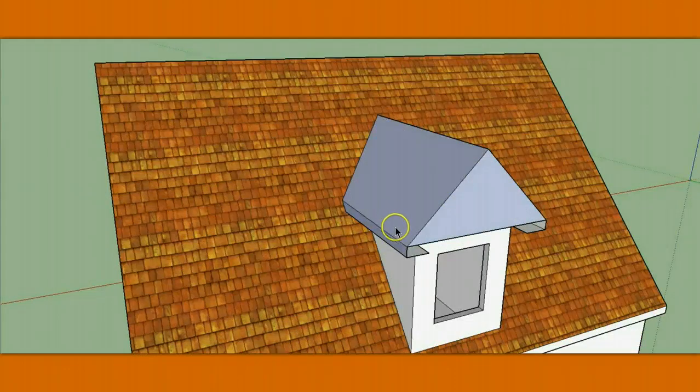Okay, good. Now, obviously, this is your metal roof. Here, this is all half-inch CDX plywood. There's flashing. We have flashing coming down here, so it comes up, and then the metal comes up. So we're not going to have any leaks. Again, 3x5, 3x4. I think 3x4 should be sufficient. It's a good-sized window, and you'll get a tremendous amount of light. So going back, half-inch CDX plywood.